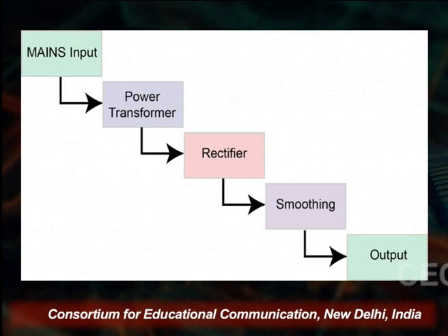These are typically block wall chargers that turn AC into a small trickle of DC and are often used to power devices such as household electronics. They are the most common power adapters and are also called wall warts. The DC voltage output is dependent on the internal voltage reduction. The transformer should be matched as closely as possible to the current required by the load. Typically, the output voltage will decrease as the current output to the load increases.